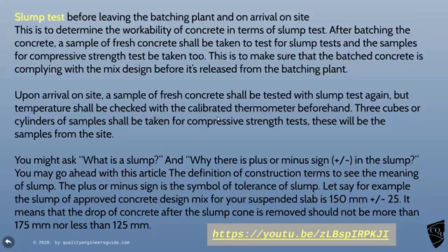After it's batched up and the concrete is then trundled off to site, it turns up on site, the fresh concrete is ready to pour, you immediately do another slump test. So your site agent, whatever, will do it there and then before it's fully delivered, just to check it's an acceptable batch. Okay. They will also cast 3 cubes before it's actually used.